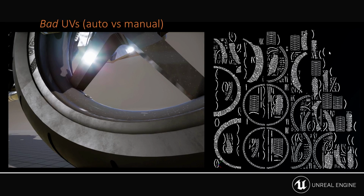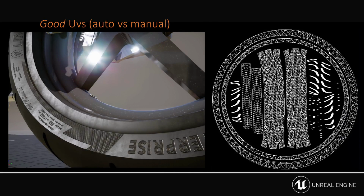To compare, here's good UVs, this idea of manual layout. We've seen that automatic UV layout, and now we have a manual layout here. You can see on the left we have some nice texture detail happening along the sidewall of that tire, and that texture is how it should be rather than just scattered around. And we're not seeing seams from the light maps, because this has been manually laid out. So projected in a specific way, you can see the rest of the rubber detail from the tire is laid out to be able to grab that texture detail very easily as well.